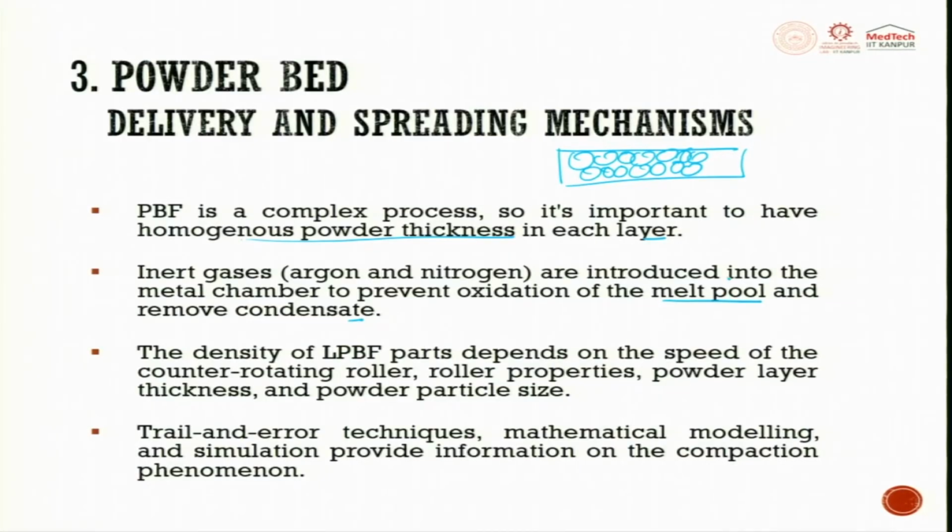So melt pool I have already told. During this melt pool, there is always a possibility of attracting oxygen, and the oxygen gets diffused into the melt pool. We try to avoid it. The density of laser powder bed fusion parts depends on the speed of the counter rotating roller, roller properties, powder layer thickness and powder particle size. All these things try to dictate the powder quality.